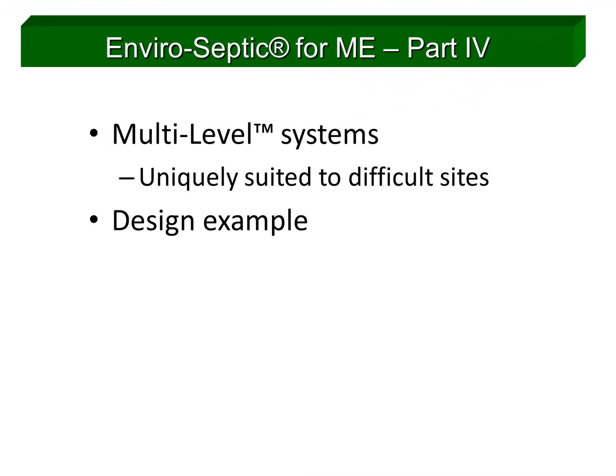In this section, I'll introduce you to the patented multi-level EnviroSeptic wastewater treatment system. This is a unique application of the standard EnviroSeptic system. However, rather than having a single level bed, there are two levels of pipe. One stacks over the other. Often applications with very difficult site constraints require a field to be as narrow as possible, and that's where MultiLevel